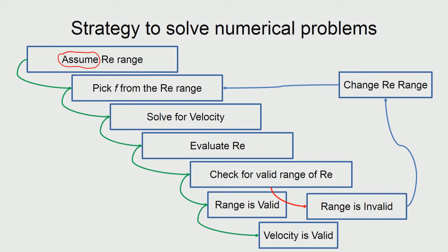For example, if you take the rough pipe expression, you do have the logarithm term. So, there will be some iteration required, and usually if you use software like MATLAB or Mathematica, you can directly solve for it. Otherwise, you could also use a calculator and use what is called a single point iteration scheme, and then get the solution. So, we would have some practice of such problems in tutorial anyway.